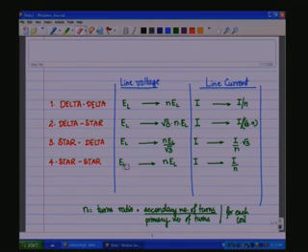So, the windings will have to withstand whatever quantity on the primary or the secondary divided by root 3. So, it should only withstand 1 by root 3 times EL and 1 by root 3 times nEL in the case of the star star connection. Of course, for the same power, the line currents will be the same, but the phase currents in the case of the star will be higher compared to the delta. So, that is where the compensation is.